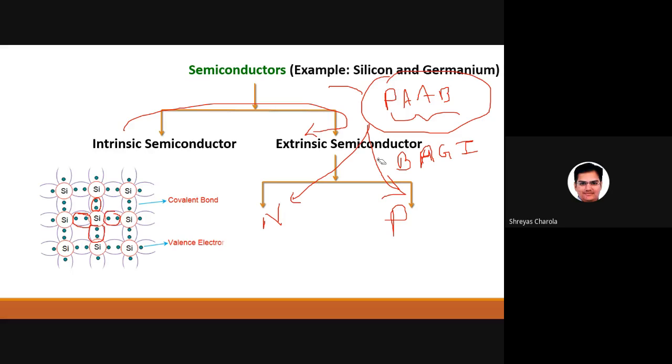The pentavalent impurities have extra electrons or holes? Extra electrons. So if you have millions of pentavalent impurities, what happens? Millions of extra electrons. So where should it come, N type or P type? Obviously the N type. Coming to this one, it's in the P type.